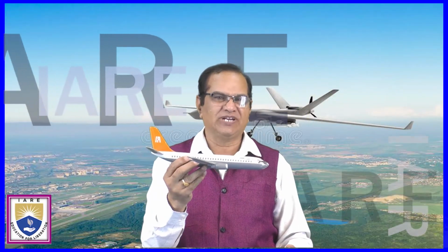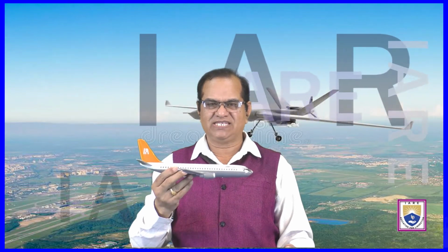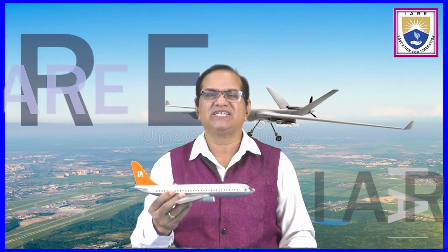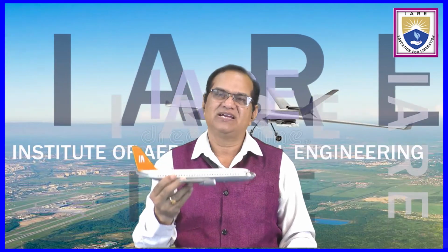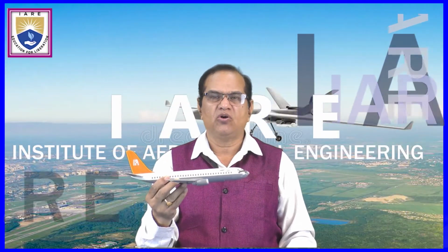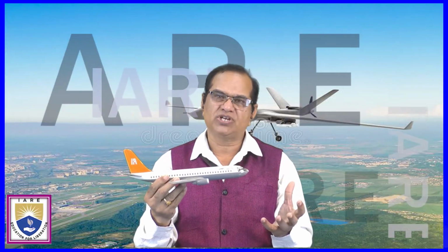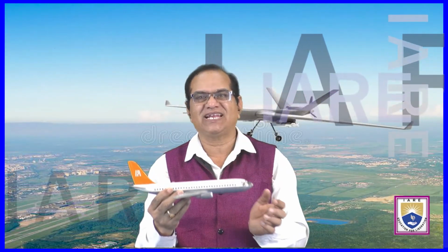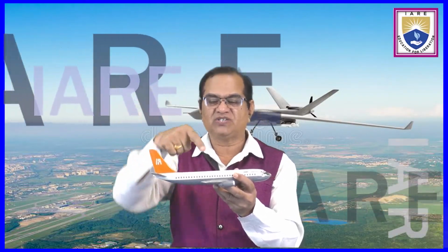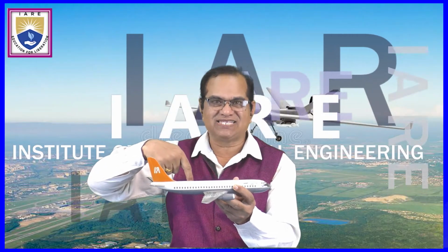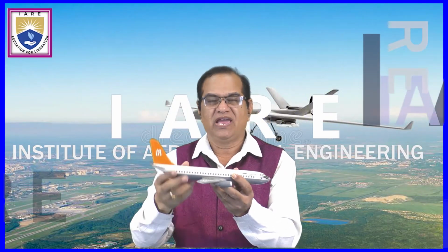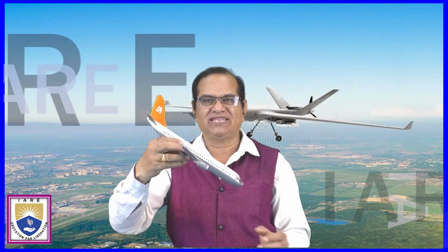If the aircraft is moving in this direction, it is a longitudinal direction, and if it is moving sidewise, it is in the lateral direction, and if it is moving up and down, it is in the Z plane or the vertical direction. So there are three linear motions in X direction, Y direction, and Z direction, and there are three rotational motions. First one is with respect to the lateral axis or Y axis. So the aircraft will do pitching. It is called the pitching.